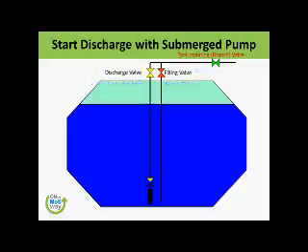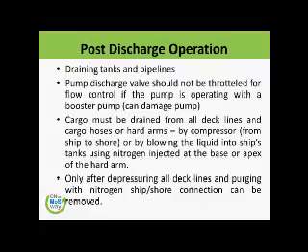Okay, we have already done the line cooling, so technically we can easily start the operation as soon as the cargo arrives. And of course we start slow, let the shore receive the cargo. Once the shore confirms that they are receiving the cargo, we can slowly and gradually top up all the pumps.